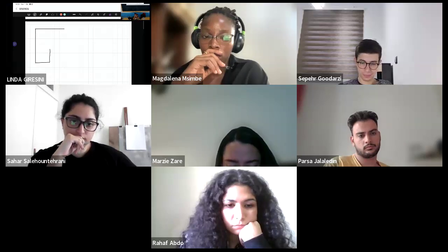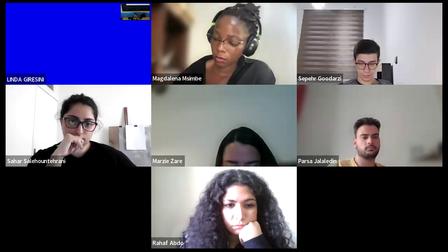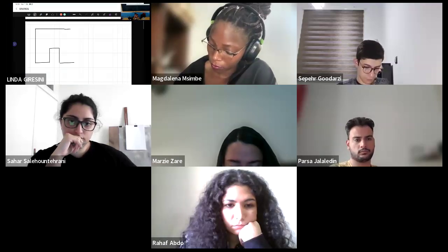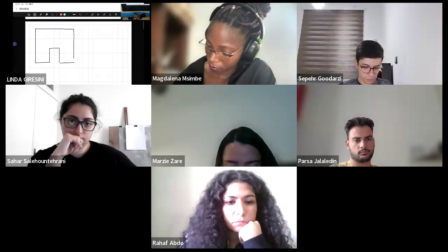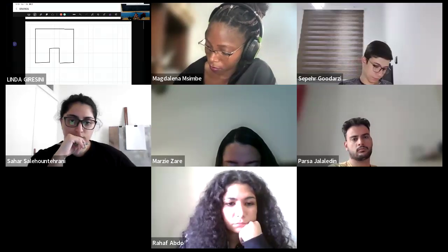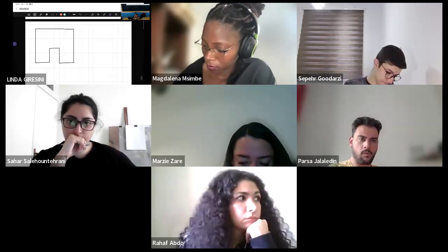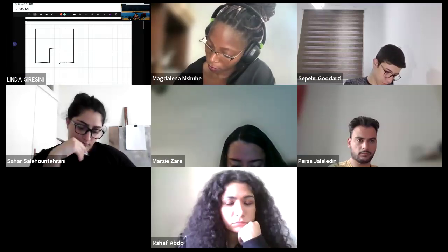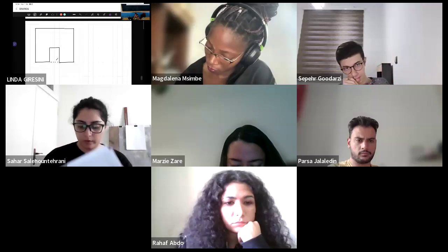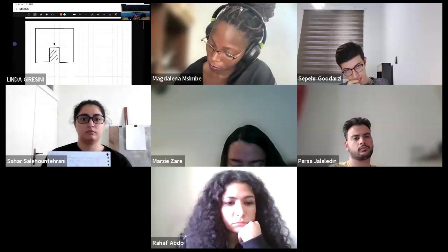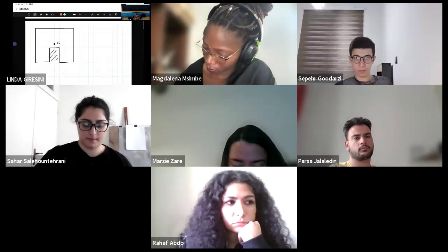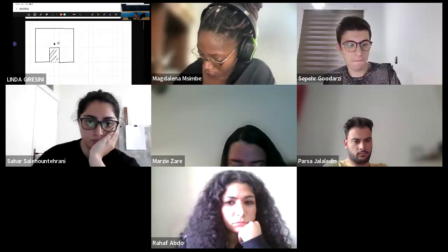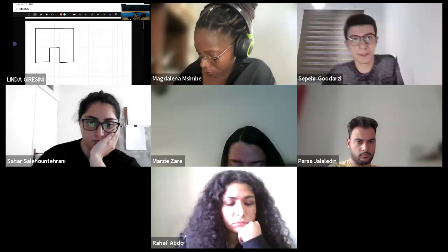Let's take this example. You have a masonry building facade like this. And you want to find the centroid of, so this is an opening, a door, for example, and you want to find the centroid. So if this opening was not here, so if this was full, the centroid would have been simple to calculate because it was the intersection between diagonals. But in this case, you have this opening, and so you have to consider it.